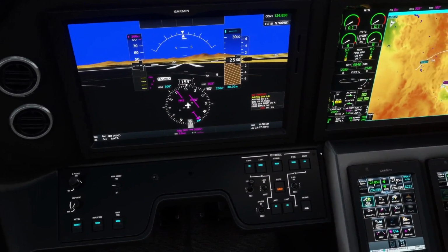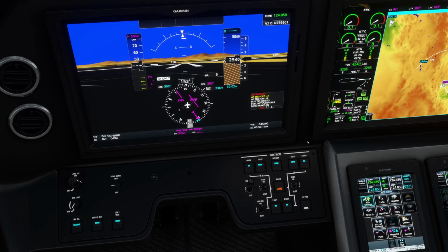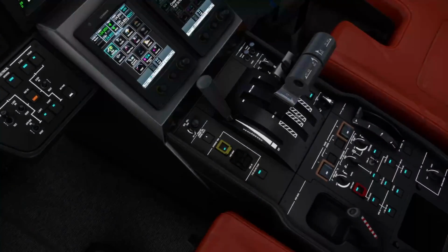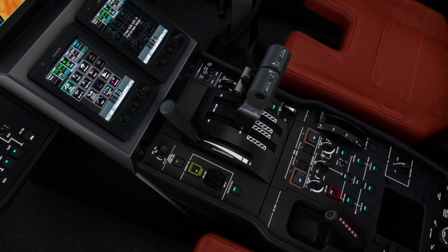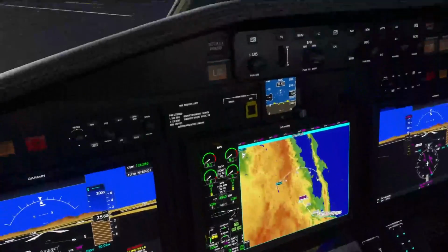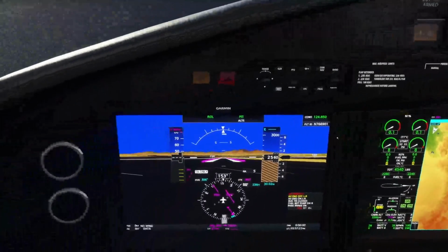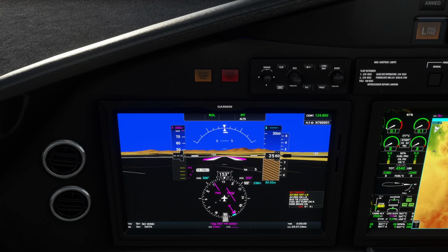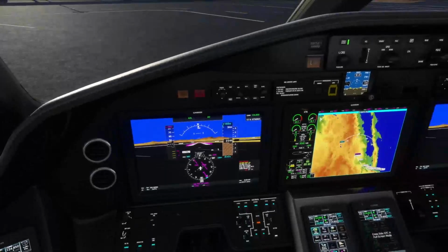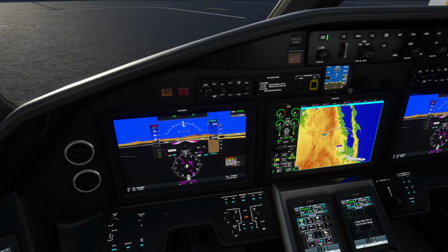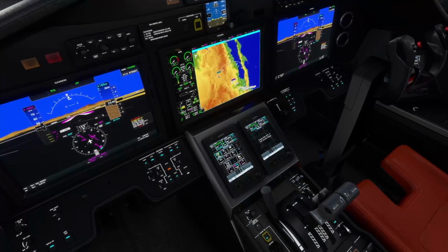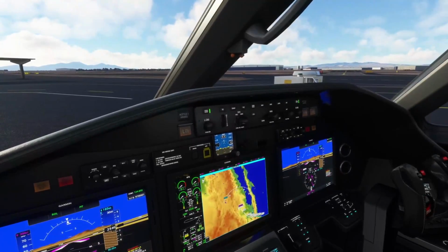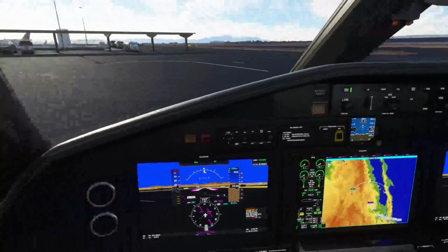All right, so we got the FMS set. Cast messages, yep, that's all as expected. Other than that, I think we can turn our flight directors on. We'll go ahead and set our initial altitude. Let's do that. We're going to start out at 16,000 feet. Okay. Speed, we're going to let the FMS take it, assuming that I don't mess things up. Okay. And other than that, I think we are good for startup. Can't think of anything else we'd be missing at the moment.